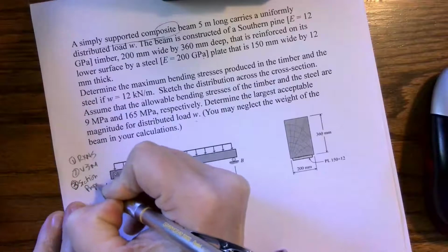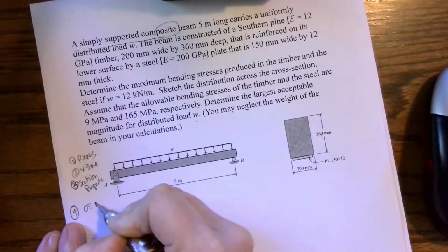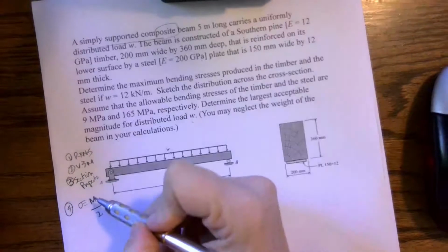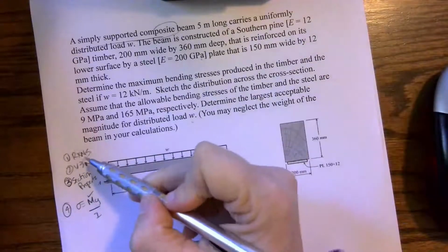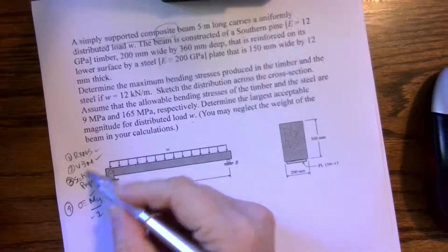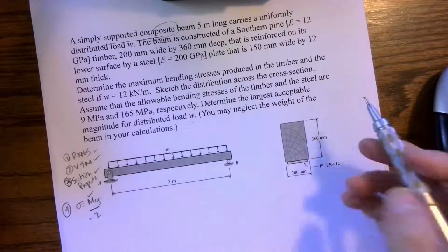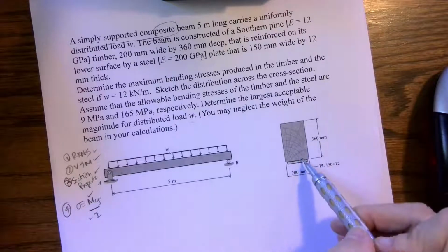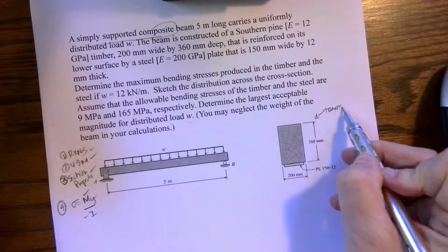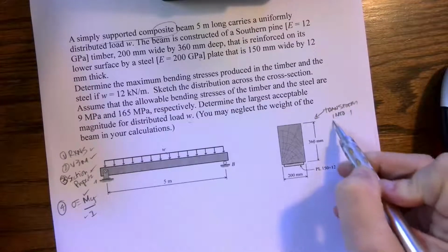And that is all before I can come into looking at my bending stress due to moment. So moment is going to come from the reactions in the shear and moment diagram. My I is going to come from my section properties, and Y will also come from my section properties. Because I have two materials, I'm going to have to transform this into one material.